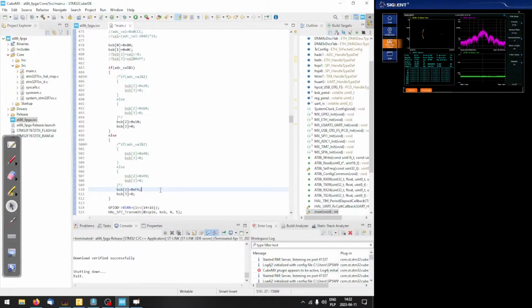So the signal is either a sine wave or an inverted sine wave, or cosine, because we don't really care about the starting phase. We expect the signal to have two states, either zero phase or inverted phase. But in our case, there is obviously something wrong going on, because there is a big DC peak in the center. So let's go one step back and analyze how it should look.